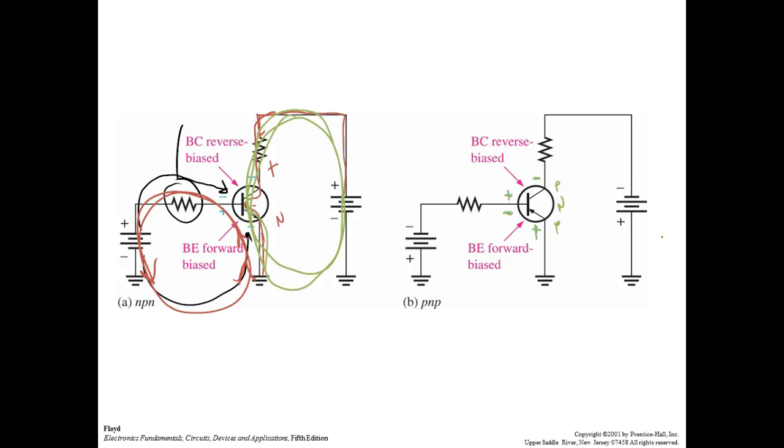So what we're looking at is this collector resistor right here. So if I put 10 volts right there, and once that collector resistor drops 10 volts, how much is being dropped by the transistor? How much? I got 10 volts applied. The resistor's dropping 10 volts. How much is dropped by the transistor? 0. Yeah, so the switch would be what we call closed.